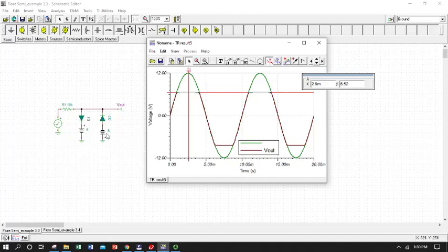So let's make sure our head math was correct over here. In this case, this point is going to have to be less than -8, effectively, minus the forward bias. So we would expect -8.7. So we're hoping to see a -8.7 here or thereabouts. And this time we were correct.